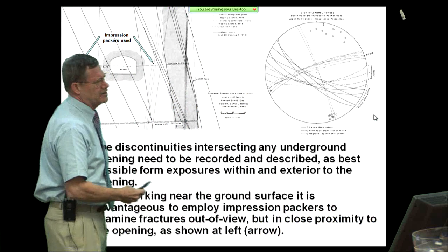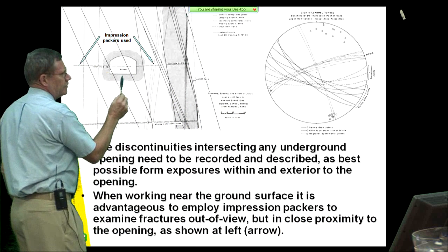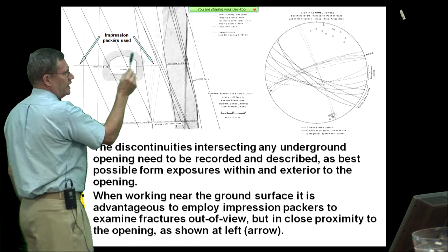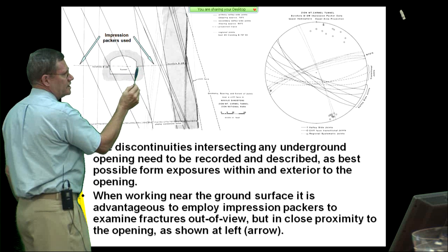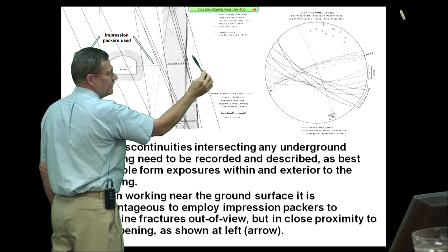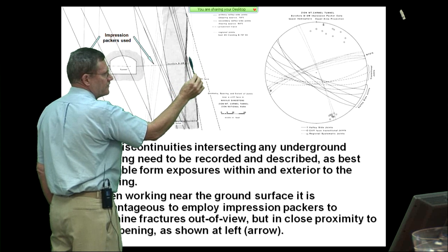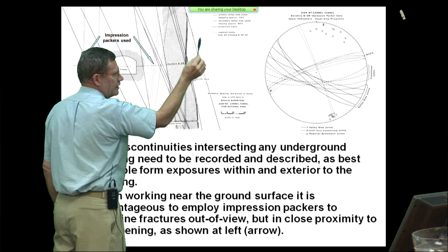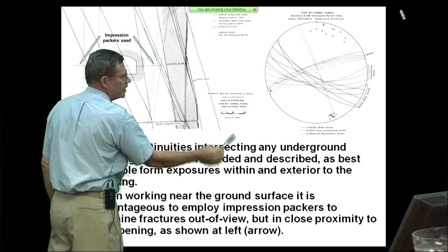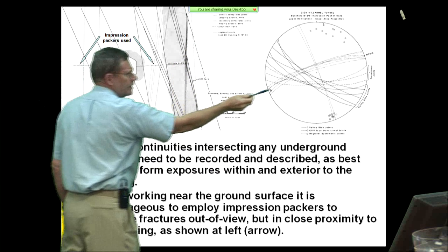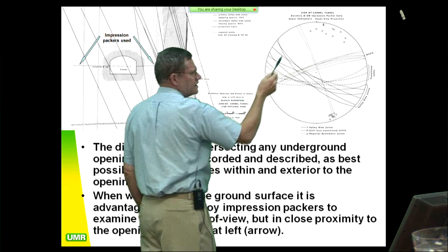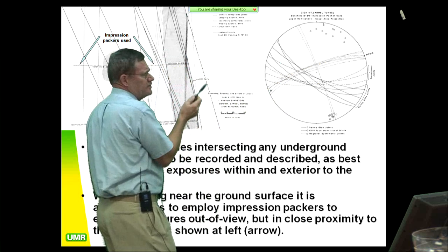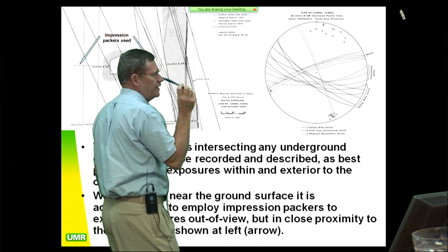Okay, so here's another side hill tunnel where we have a tunnel opening for highway, and then we have an annulus between the tunnel right here and the cliff face out here. And this is where the cliff face failed. This line along here, the cliff went kaboom and came down. And what I'm doing here is I'm plotting my strike and dips of my joint sets. And this is just what I was just talking to you about over here a few minutes ago.